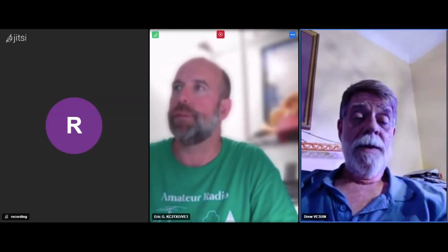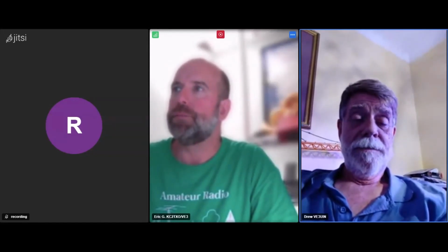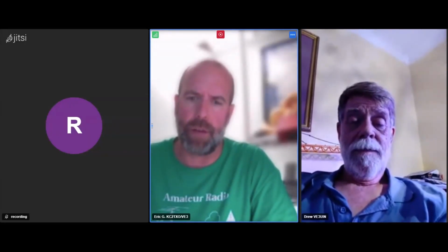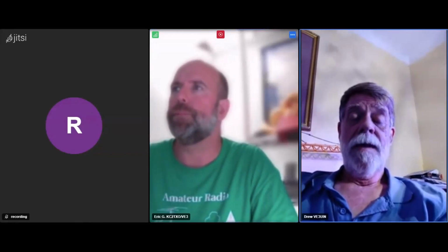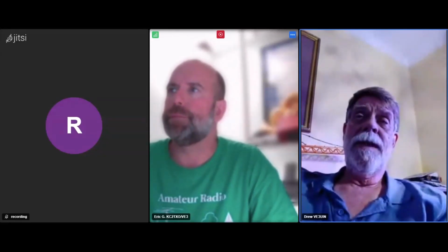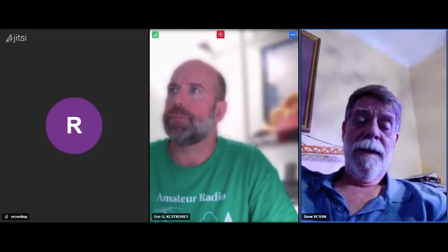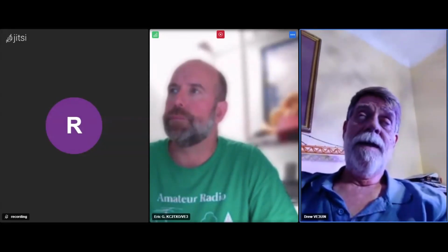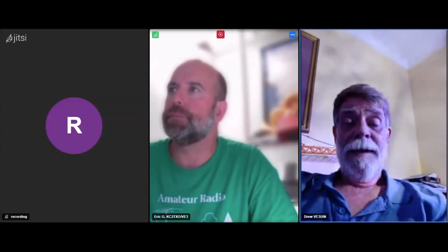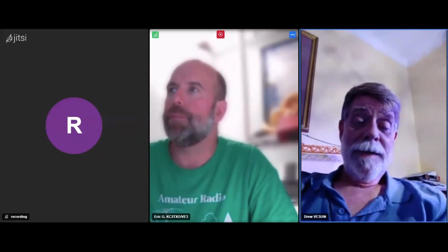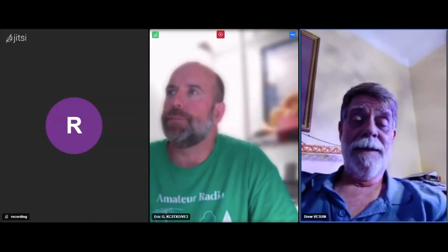And you can use those as an inverted L. I think Peter had one of those last year when he was here for field day. They work really well. If you put the balun basically at the corner and drop the 25 or 30 feet down, and then you shoot out the 90 feet, you've already got a lot of wire in the air, to be honest. It would be hard not to get somewhere.